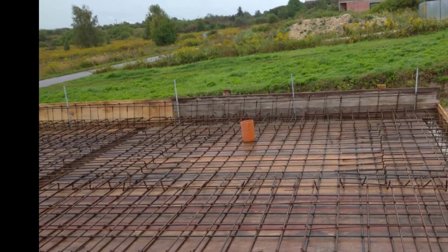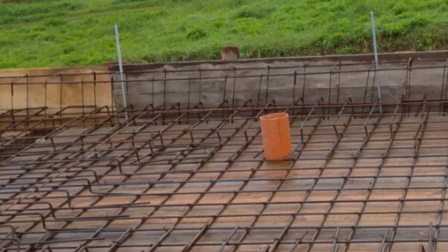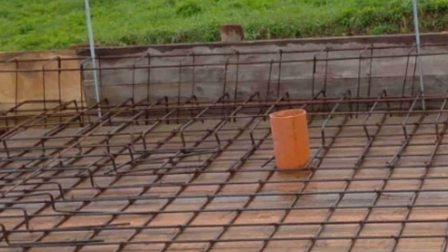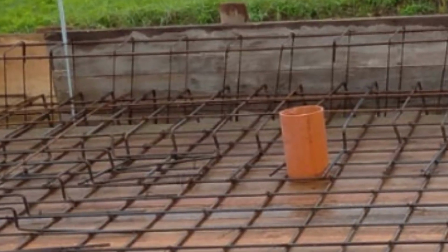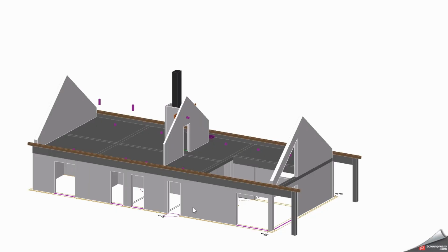Based on the information I had found on the internet, I then gave careful thought to the matter of diffuser placement, and during the reinforcement of the ceiling slab I carefully positioned within the formwork sections of 160 mm diameter drainage pipe, which were left over from the earlier phases of the construction.